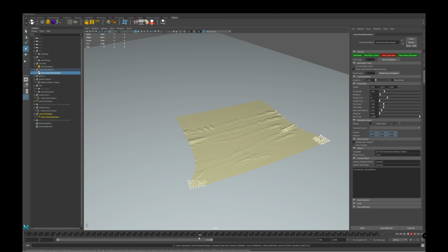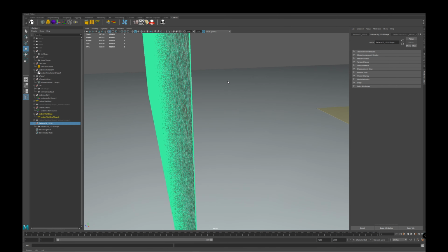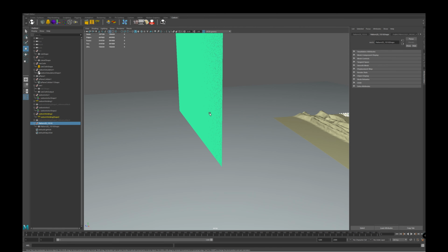Of course, we may want to deactivate the original welding at frame 400. There are endless activation and deactivation possibilities here. Now, as a final step, we will just add the render mesh and use the deformer. So we add the render mesh into the scene, and here is the render mesh, and you can see it's high resolution and it's also a volume.